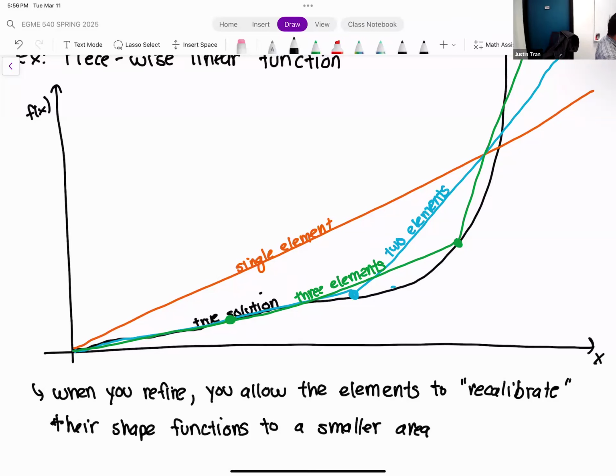And in fact, we've already done this. If you think back to activity one, there was a part of that activity where I had you refine the mesh around the hole. And if you remember what that simulation result looked like, we had a concentration of stress around the hole just because of how the plate was loaded at the time. By doing so, we were applying this effect right here, where we know that we're going to have a high variation of stress within that area, stress concentration. And so we refined our mesh in order to better capture that variation.